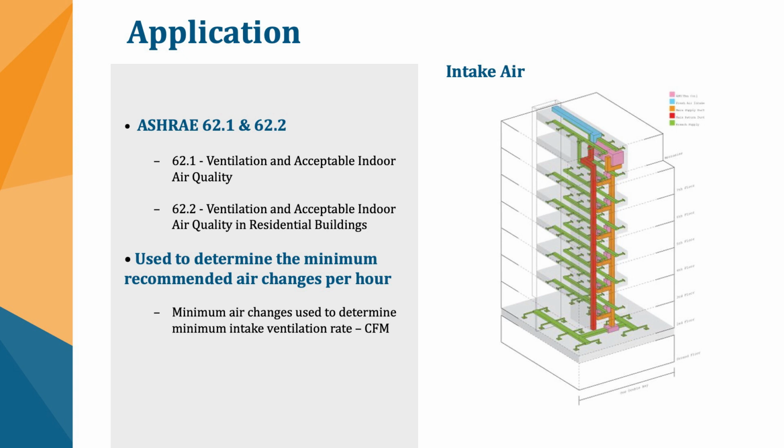If you're not dealing with a dedicated outside air system where you've got an intake air system, you certainly don't want to have that intake air system running constantly throughout the day. You don't want to have to condition more air than you need to keep a certain level of indoor air quality.